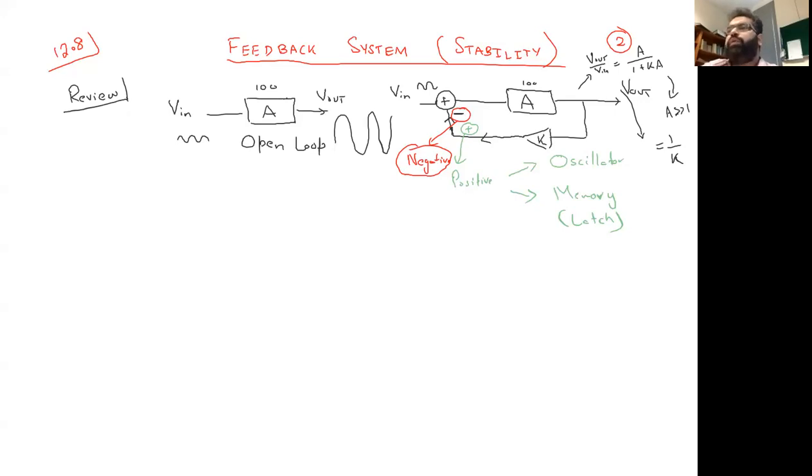Till now in this course, we didn't touch the topic of phase, and phase is very important. Phase can make the system unstable even if your magnitude is fine. For example, a positive magnitude is considered negative feedback, but if the phase is more than 180 degrees, the net conclusion is going to be negative, and then ultimately you are in totality giving a positive feedback.